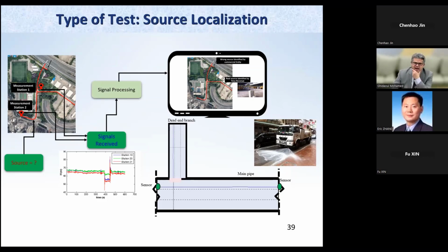So in this system that they had in Hong Kong, they got these sensors and they were giving them pressures in real time. And it's fun initially, I think, for engineers to see it. But once they see something bizarre, they get agitated because they want to know what's going on. And same as a human, when you go to a doctor and they see some signal, you get a bit stressed. You want to know what is going on. And engineers are no different when they see it about their system. So at 4 o'clock each day, they were seeing a drop of pressure of about 10 meters. We happened to be in their office one day, and in fact, they called us, and we went and looked at the screen, and this is precisely the signal you see around 4 p.m., a drop in the signal, and that's from different sensors, a drop of about 10 meters of pressure.